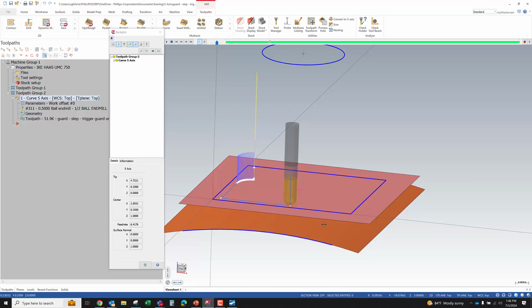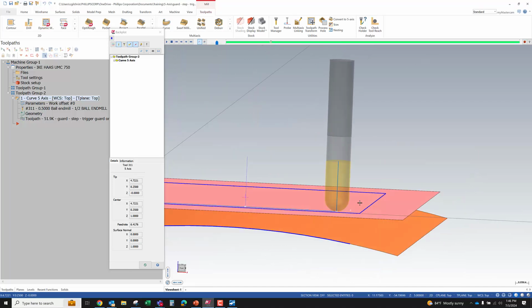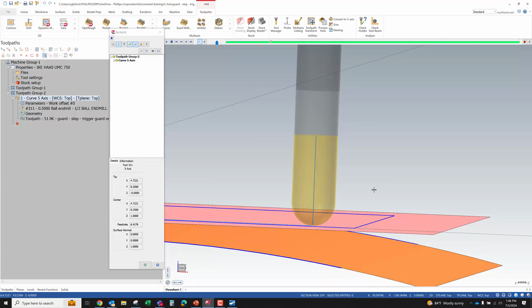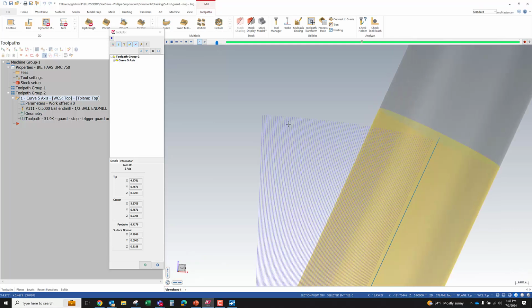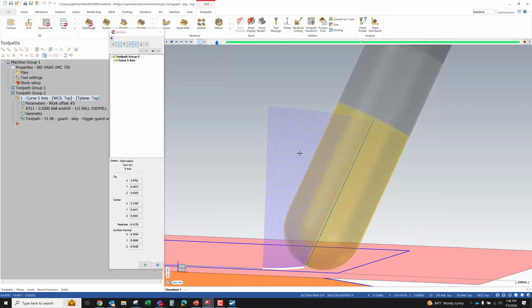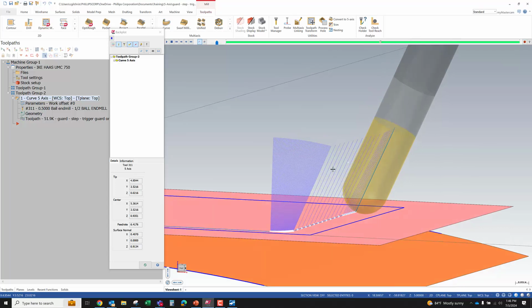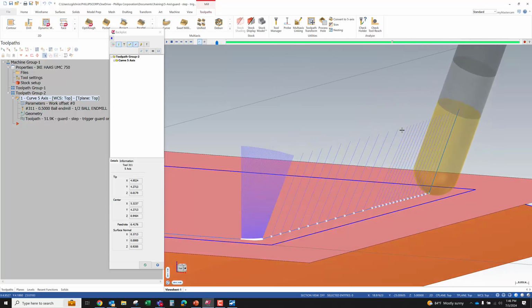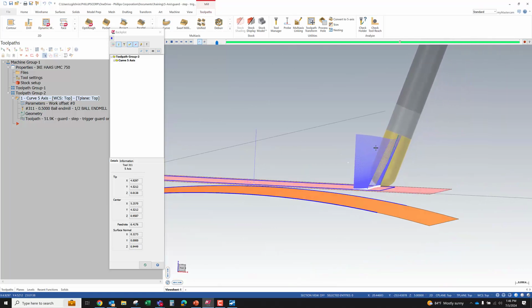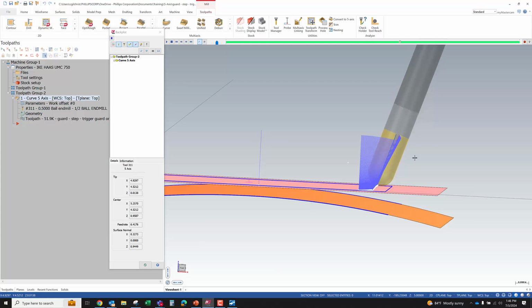And the final piece of the puzzle for a 5-axis, I want smooth rotation on the machine. And that generally is going to mean more vectors for rotation, a combination of that, and even spacing between the vector positions within reason. So here, this is going for 100 or 150 thou between, and then it jumps down to like maybe 80 or 50 thou between. I don't care about that. That's going to be fine, because if I look at this from the side, I'm getting rotation.